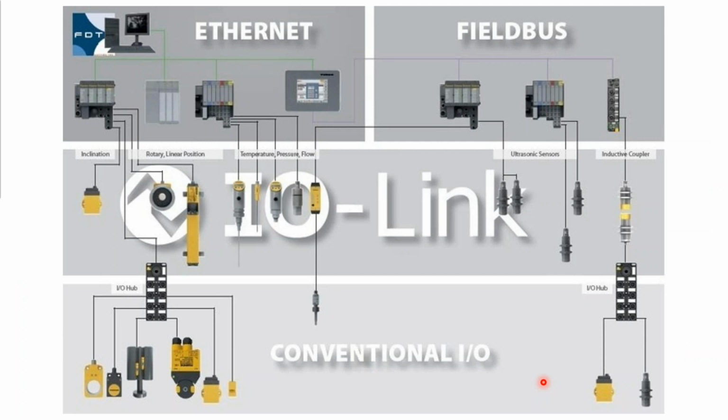Well, the top layer, we still have our field bus. These days, the most common ones are Ethernet. The two we run into the most are Ethernet IP and Profinet, which both have lots of different options for putting things in I/O link. Then this middle layer, now we've gone to intelligent sensors that have the I/O link microchip embedded in them that's giving us the connection data, the measurement data, the diagnostics, and all of that. Now I've heard somebody say it, I think it was Turck, and it really plays well, is that we're now putting intelligence into the last meter of cable run.